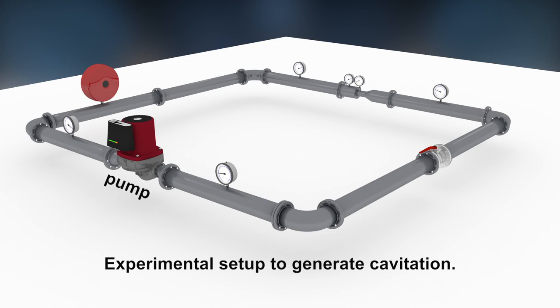When pumps circulate water through piping systems, cavitation can occur where the pressure is lowest, at the inlet of pumps and in narrow pipe sections. If the pressure at the inlet of a pump is low and approaches the vapor pressure, cavitation can occur at the pump impeller, as we have seen at the ship propeller.